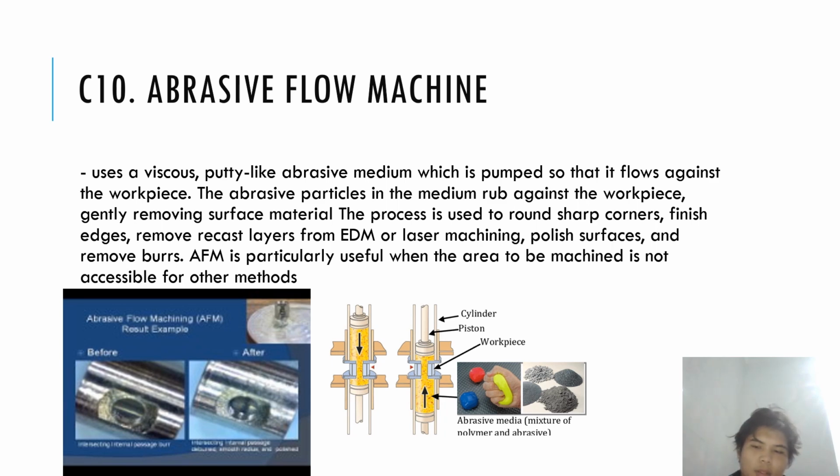So actually, I'm going to explain from the picture. The mixture here, the abrasive media, is pushed into the workpiece. The workpiece has some space to let the abrasive media go out. So it's going to be smoothing the holes.